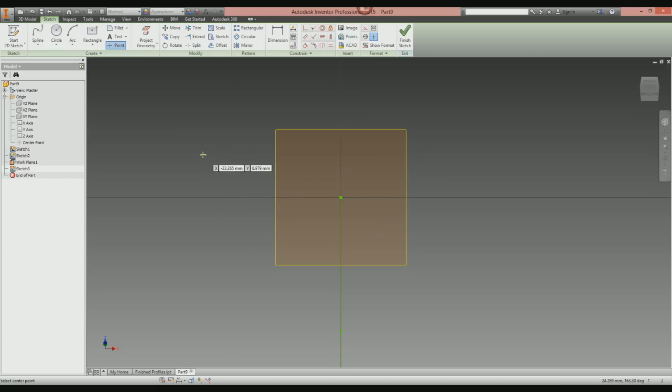So I'm going to create a point, say here, point there, point up here, another one there, another one about there, another one about there. Okay, and I've got to go through the rigmarole again of making sure all the points line up. The reason I'm doing that is because if it's an off-shaped spline, if it's not symmetrical, you're going to start your loft in a bad way. The profile that you're starting the blend from is going to be off-center, and you're just going to get this horrible, ugly-looking solid sort of blending into another profile. It's just going to look awful.